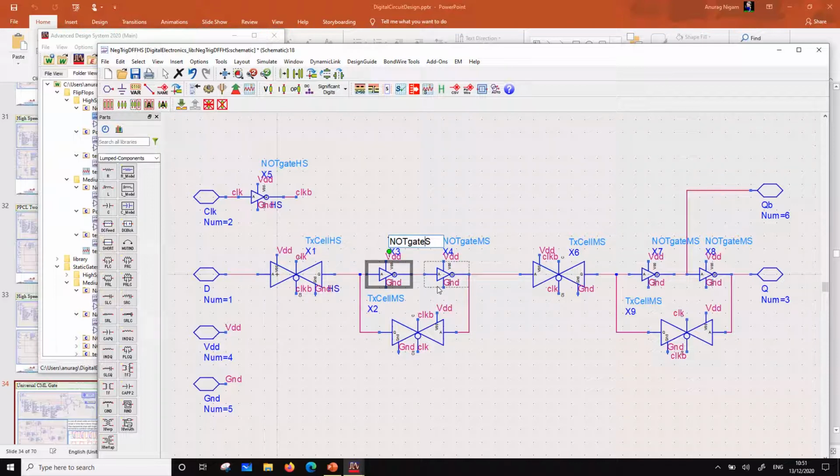All you have to do is this. We also do this in VHDL, right? In VHDL, every sub-circuit is a black box. You can always change the black box. This is what happens in the case of architecture and entity. For any component, you would write a configuration to change the entity and architecture pair to represent an instance of a component. That's what happens in VHDL also.